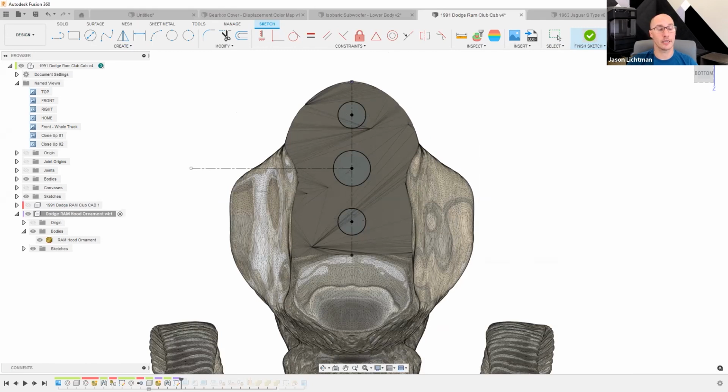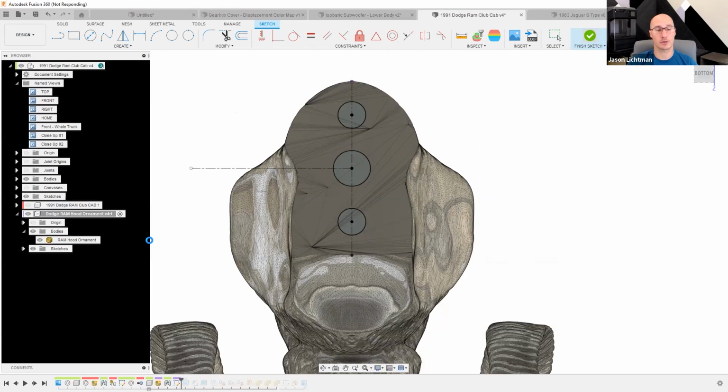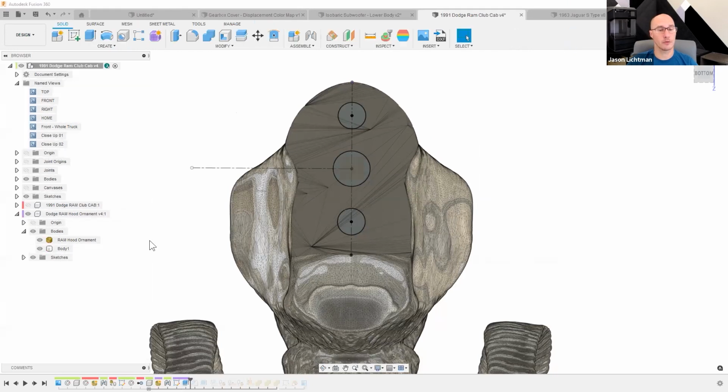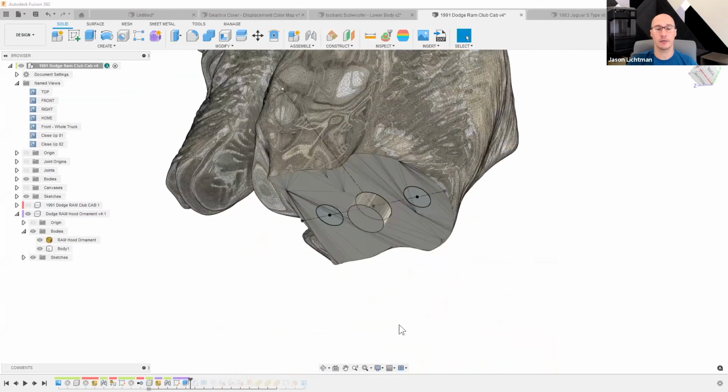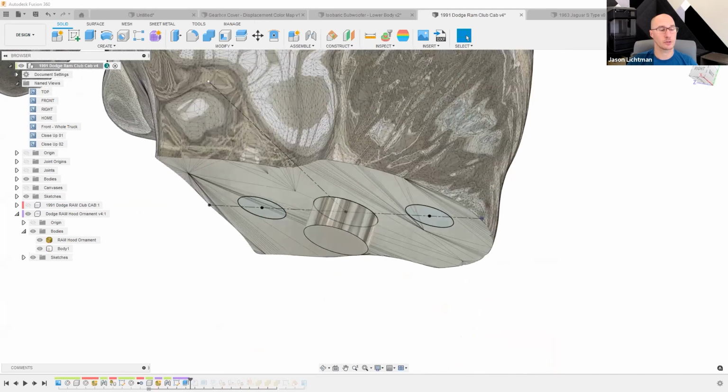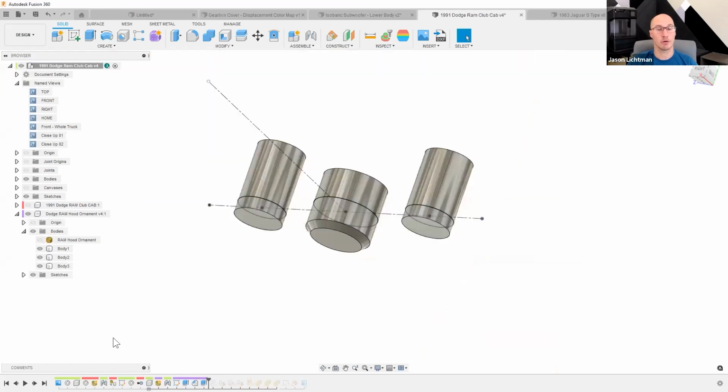So for example, I could use the extrude feature to create that boss in the center. Give it a moment for it to show up. There it is. So here is the boss in the center. I'll also go and add a chamfer to it. At the moment, it's a separate body, but it's a solid body. I'll also show that you can create the feature that'll end up being the threaded bosses. Right now, sorry, they're just bodies, cylinders. Now I added the thread to it.